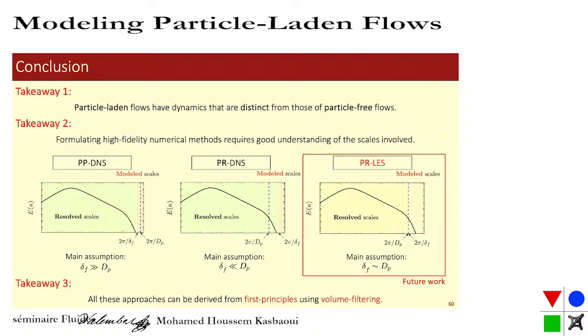Now, another thing that I would like to talk about very briefly is particle-resolved LES. If you want to do particle-resolved LES, you're going to be in that configuration where the filter size is on the order of the particle diameter. So you're resolving the sphere, basically, in the flow, but you're still under-resolving the flow on the scale of that sphere.